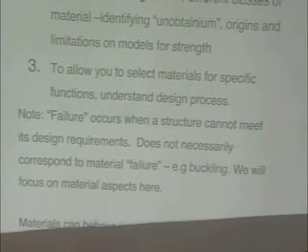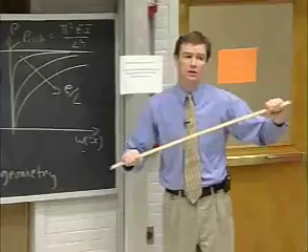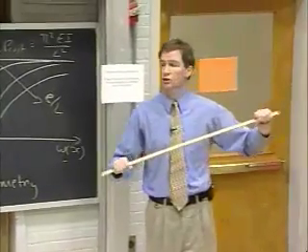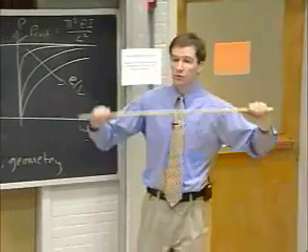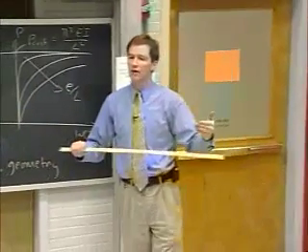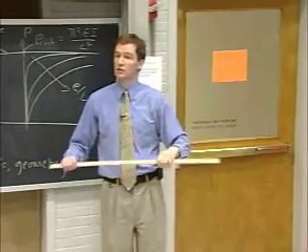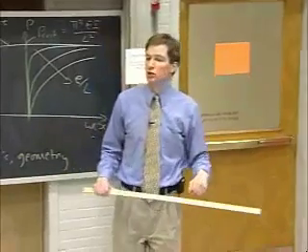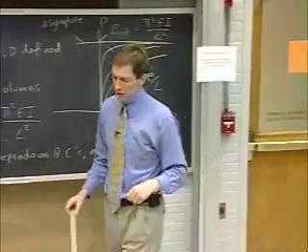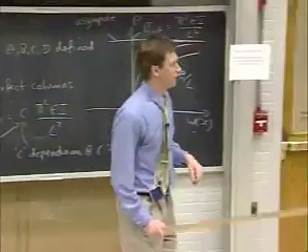That we've looked at for an axially loaded rod, we might want, for maximum stiffness, a high Young's modulus over density. But for a beam in bending, we want a high value of the square root of Young's modulus over density, and we're going to explore those same relations for strength and also to prevent fracture occurring.